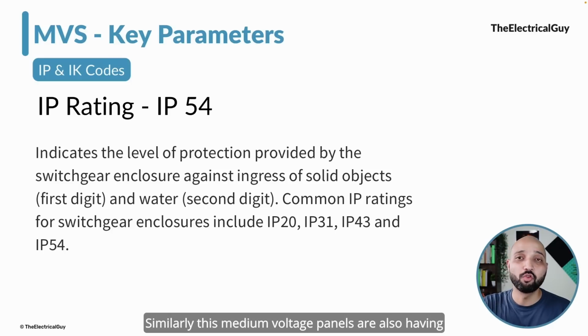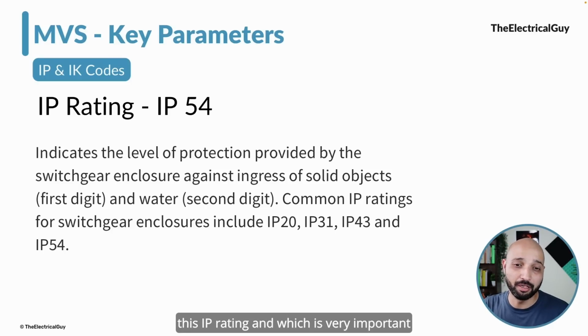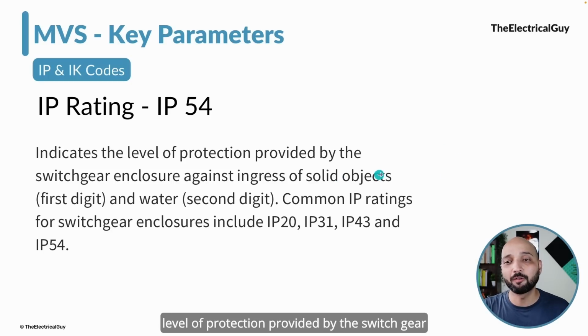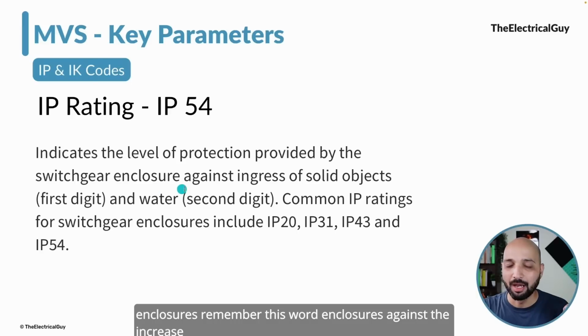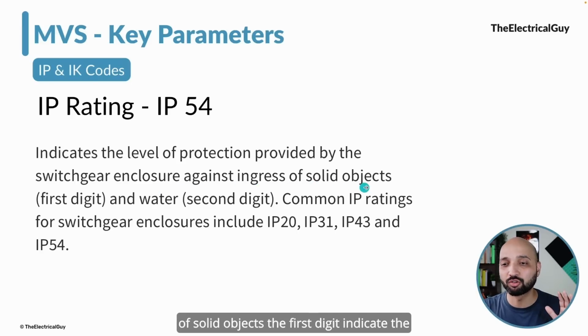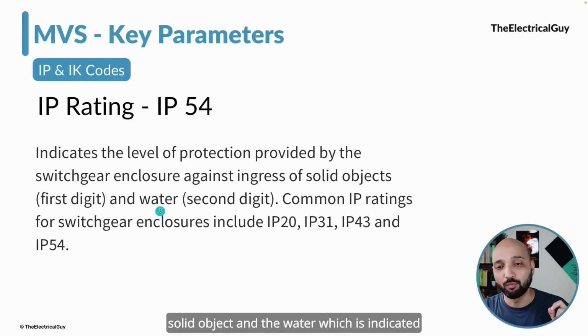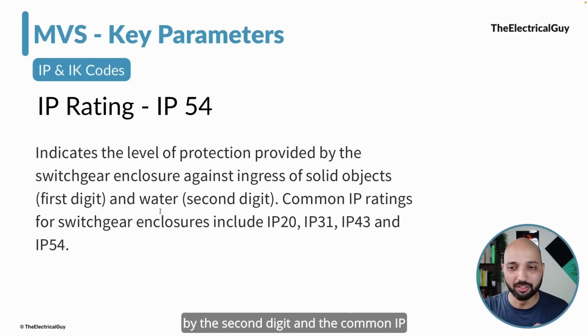Similarly, medium voltage panels also have an IP rating, which is very important. It indicates the level of protection provided by the switchgear enclosures. Remember this word, enclosures, against the ingress of solid objects. The first digit indicates the solid object, and the second digit indicates the water.